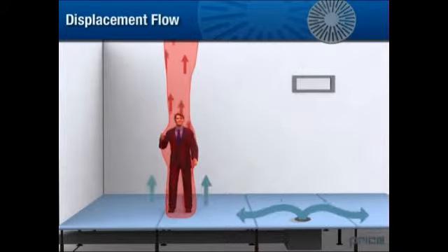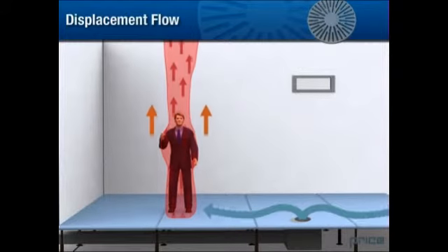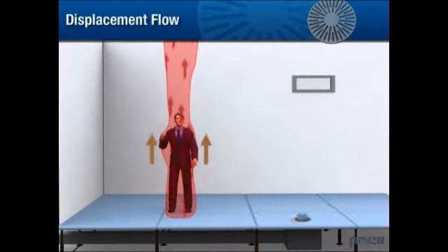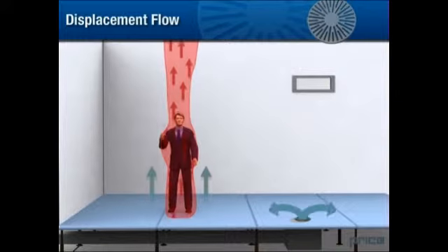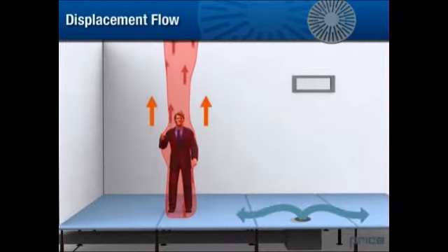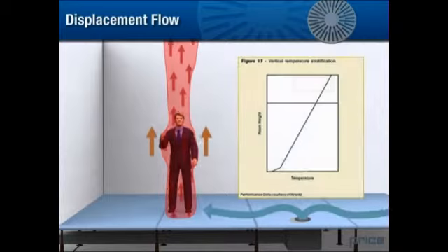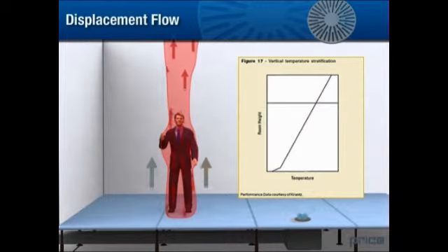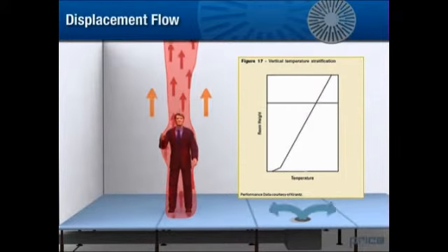The upflow, however, is determined only by buoyancy and not by inertial force. Therefore, the flow velocities of the rising air are extremely low. As a consequence, the vertical temperature gradient is much more pronounced than that of turbulent flow.